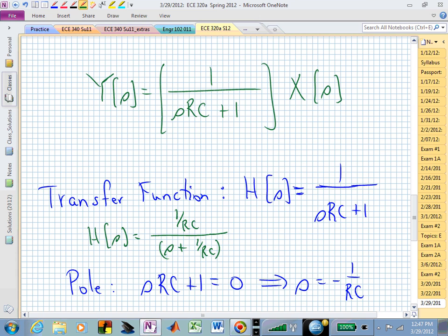Now, what I want to do when I'm talking about Bode plots is concentrate on particular values of this complex frequency variable s. I'm going to replace s with j omega, meaning I'm going to be walking on that imaginary axis, the vertical axis. And that omega value is only going to be from 0 to infinity. It's positive.